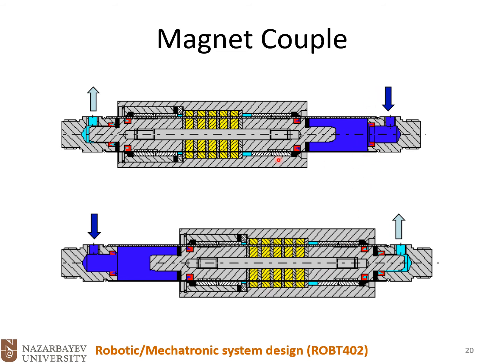But what is the mechanism of moving forward and backward? It's just pressurizing one chamber and depressurizing the other one, and vice versa, to move forward and backward. So basically we are moving the internal cylinder, and the internal cylinder then will move the external carriage.